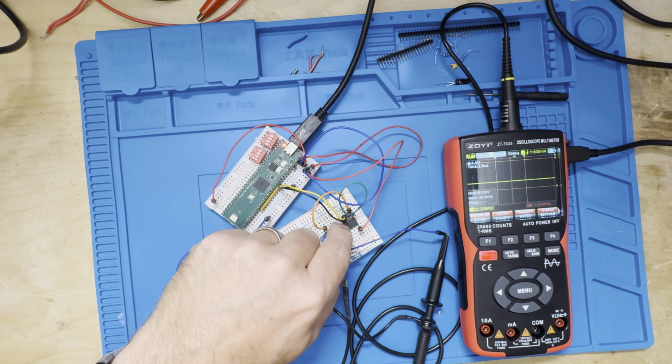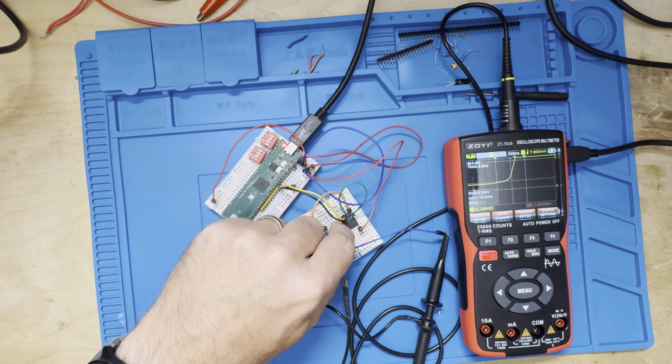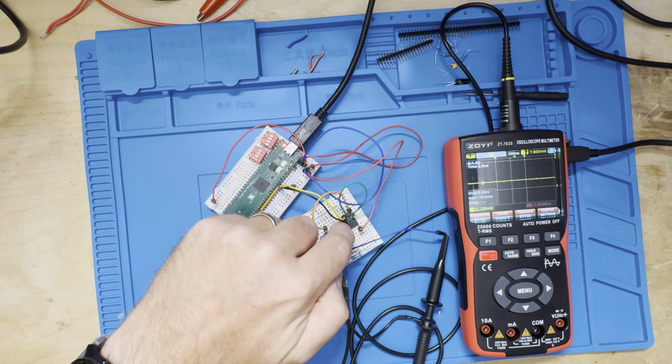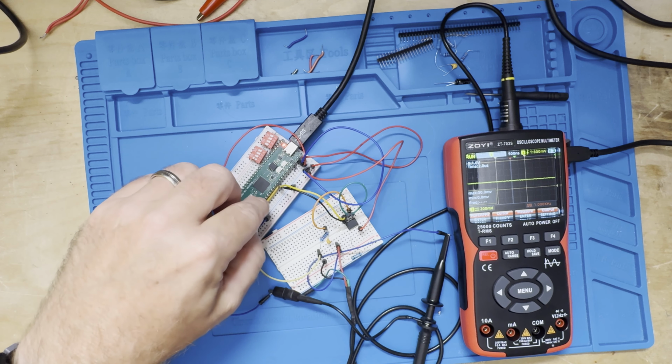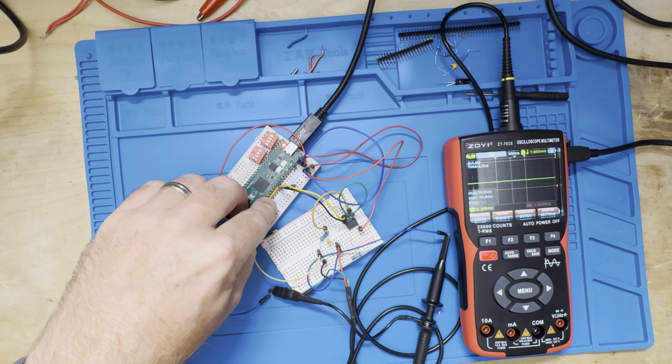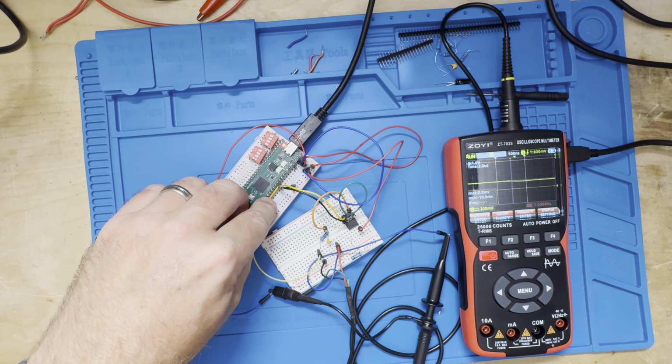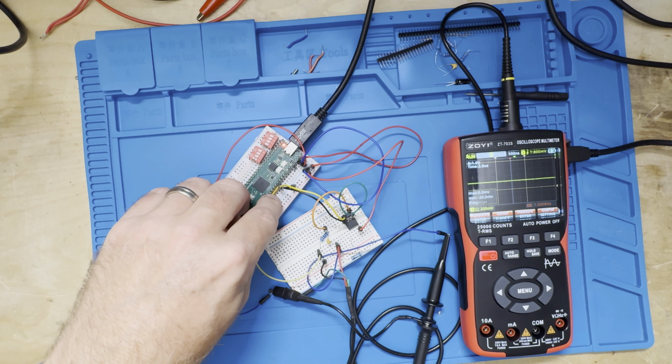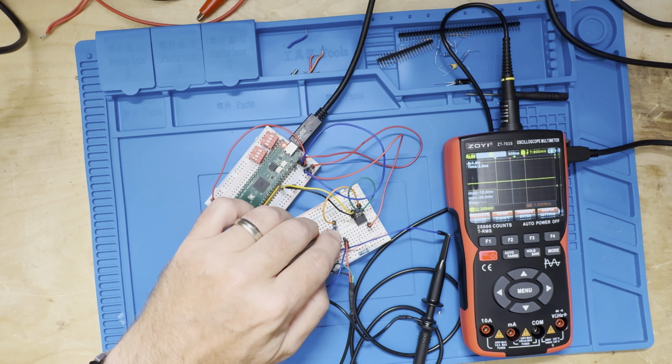What I've done is I've wired up my op amp again. The op amp is still in a unity gain mode, so it's serving as a buffer so that this circuit on this board doesn't weigh down the ladder with too much of a load that would distort the DAC's operation. And then we run it through an RC circuit to remove the DC component of this waveform. So I get 1.6 volts positive all the way down to minus 1.6 volts. I get this AC waveform out of this capacitor that I can then use to drive an audio source.